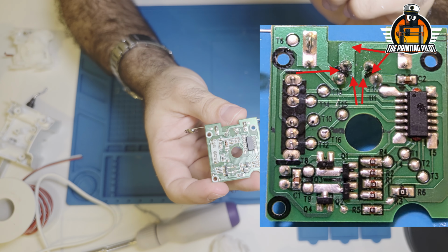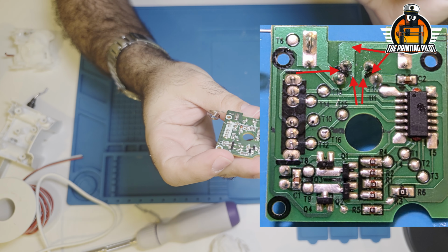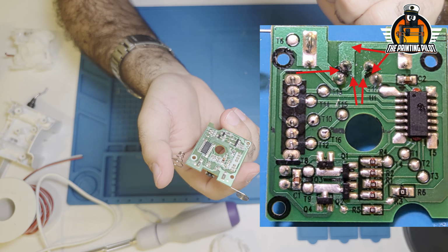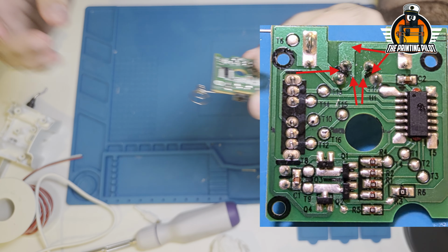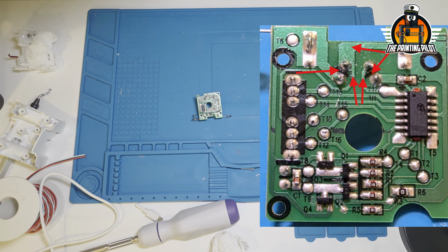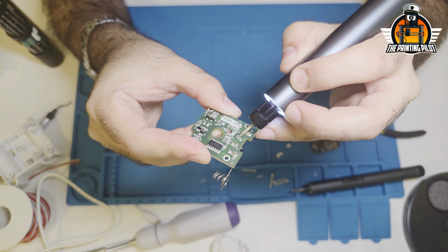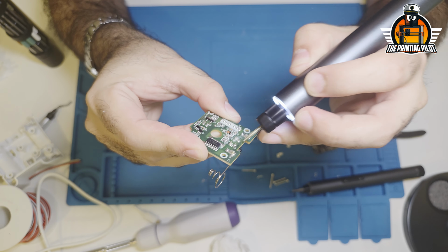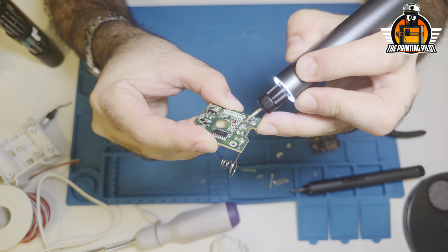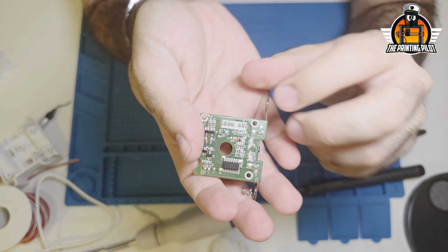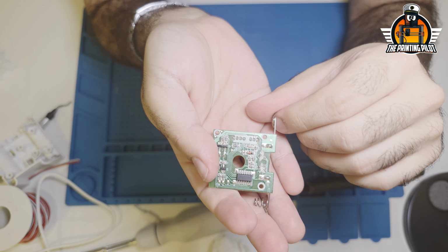So what we're going to do is use a knife or a Dremel tool to cut all of the surrounding traces to the button. It's only 4 traces, and I'm going to show it in the picture and just do it. And I'm going to do it with a Dremel tool. And after cleaning a little bit of the mess we made here, we still have those 2 points that we're going to solder to.